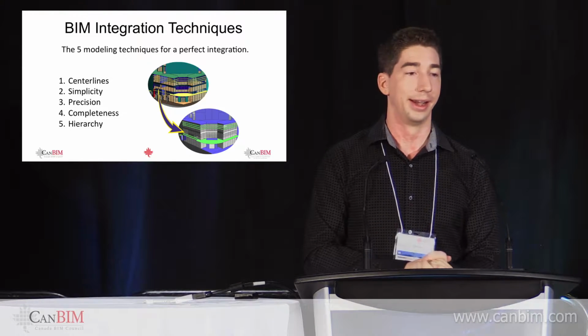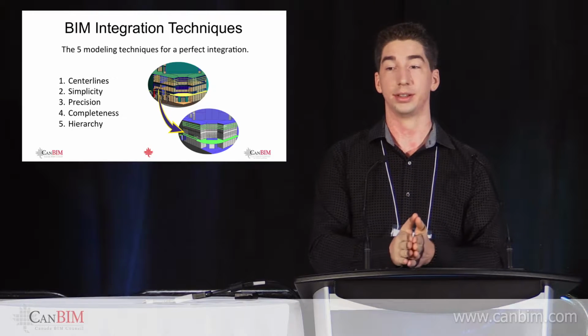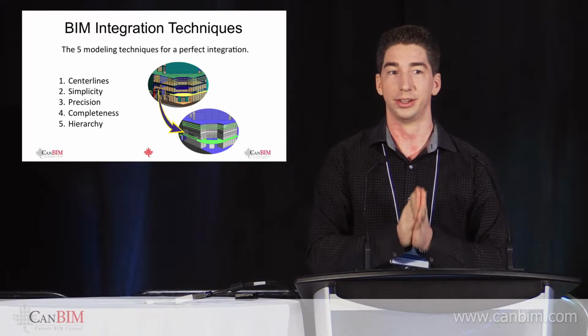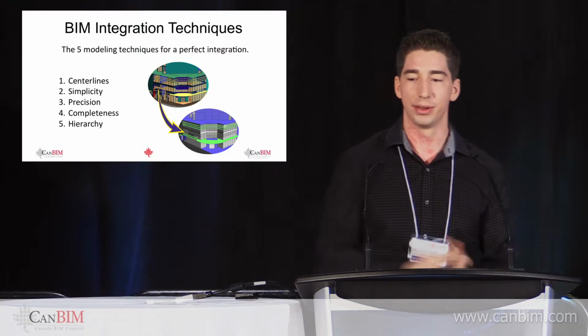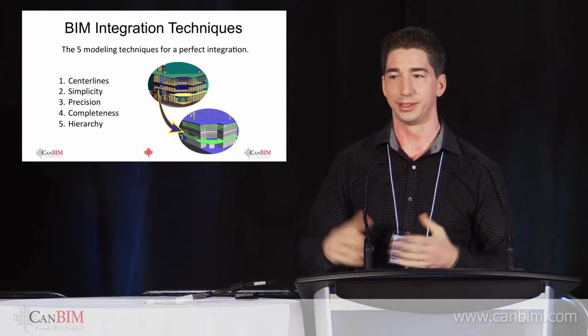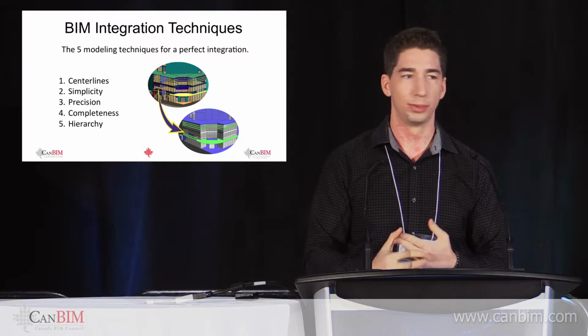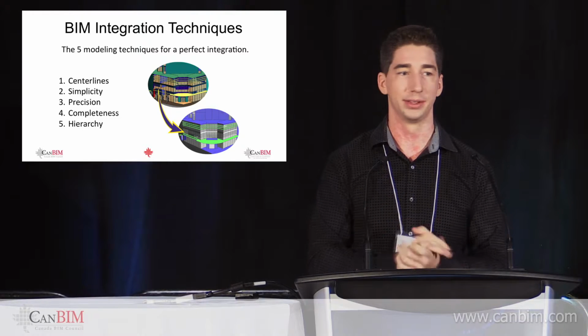It's very simple. And actually, it's much more simple than the way that you guys design. Because it's a level of detail 150, it's actually supposed to be simple. So the idea behind it is that we draw according to our center lines. We draw very simple, thin modeling walls. Very, very precise, a little too precise, kind of AutoCAD precise. Everything's got to snap together.